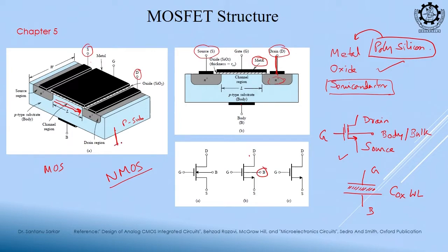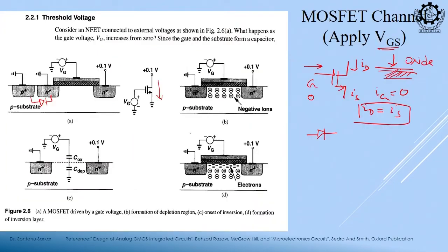That will not be of use. So, this diode should be in reverse bias, right. So, P should be connected to what? Lowest potential available, so that it is off.